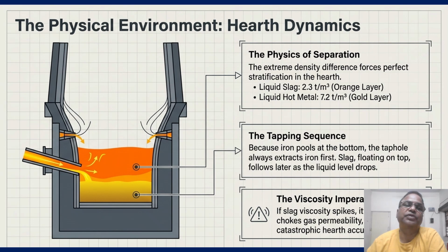Slag is not a waste product, it is a liquid engine of the furnace. So today we focus on oxide balance, the basicity trap and the magnesium anchor. These are the factors we need to introspect with the BF team.